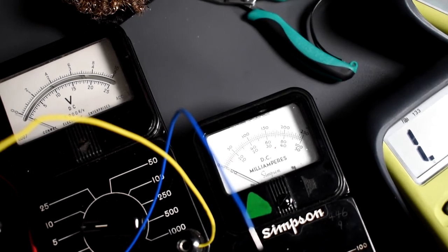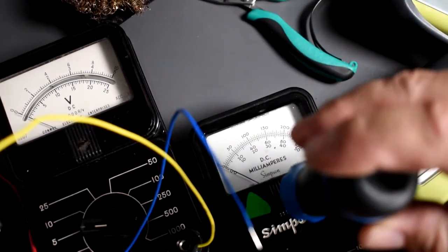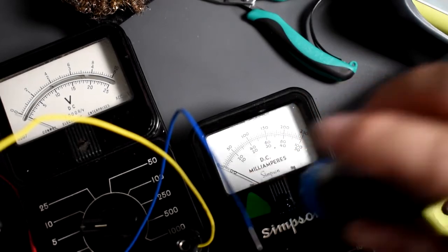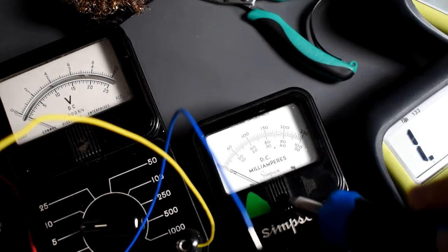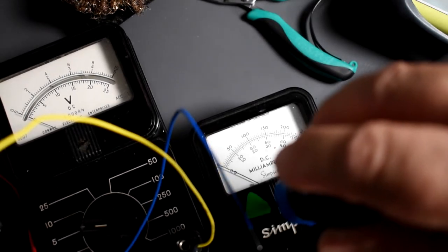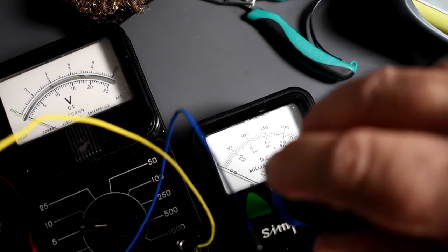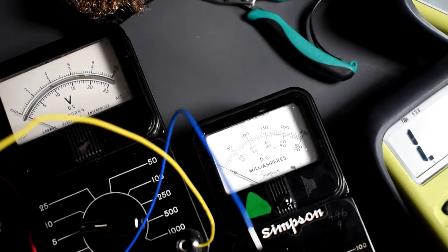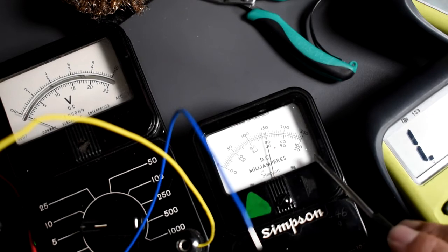So sometimes those analog meters, sometimes you just need to calibrate. So you will just turn this screw here, it's a calibration screw. Okay, here. Now we have the needle at 0. Now we energize the circuit again. See what reading do we have? We have a range of up to 10 milliamps. Do we have a scale that says 10? No, we don't. But we do have a scale that says 100.